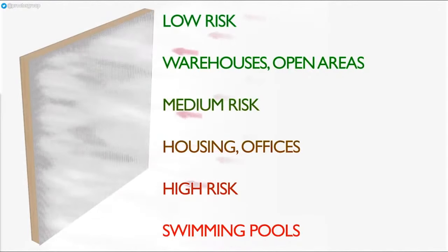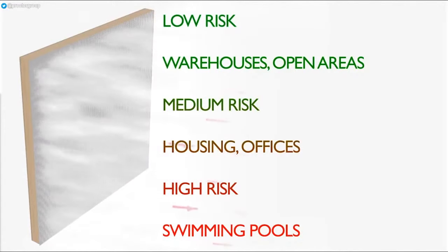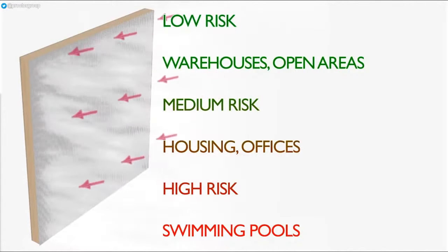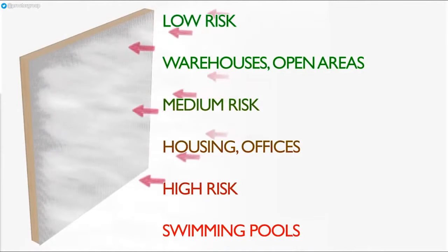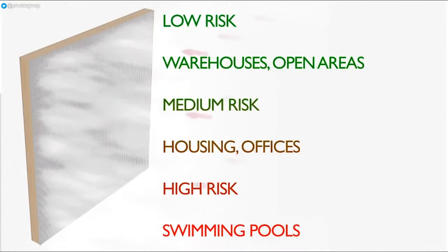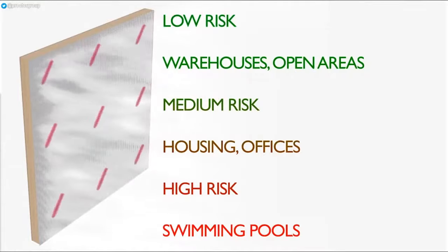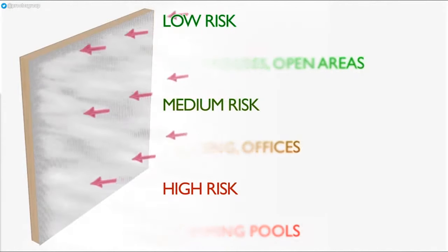In all cases, ensuring the integrity of the vapour control layer is maintained is very important. Any rips and tears or puncture damage to the membrane will provide a path for moisture vapour ingress. Heavier, reinforced membranes are therefore preferable, as not only is damage less likely to occur, but it is also less likely to spread across the membrane surface than with unreinforced membranes.